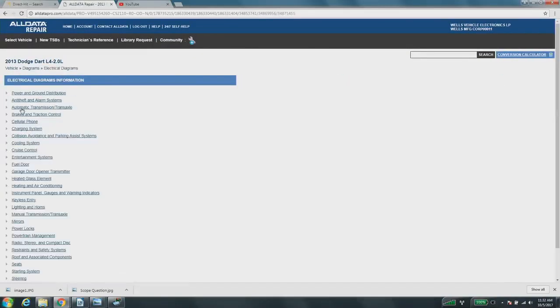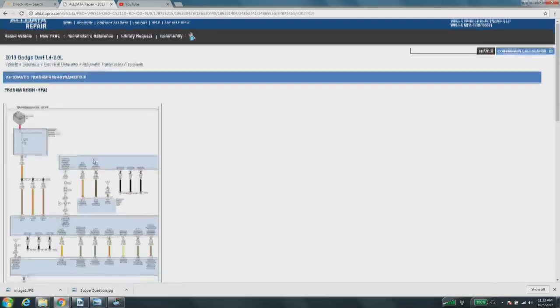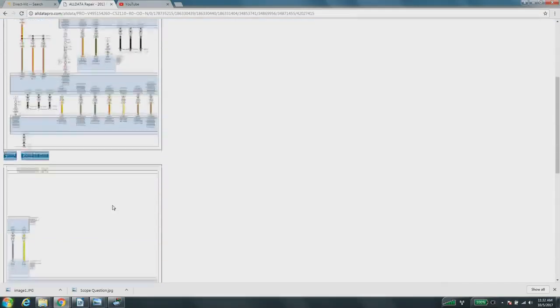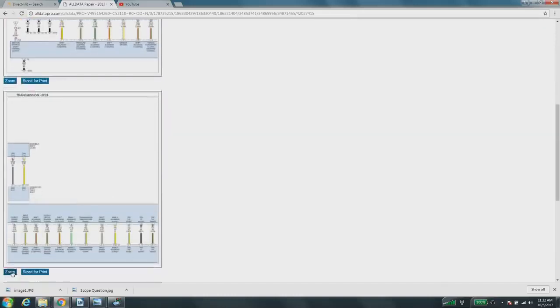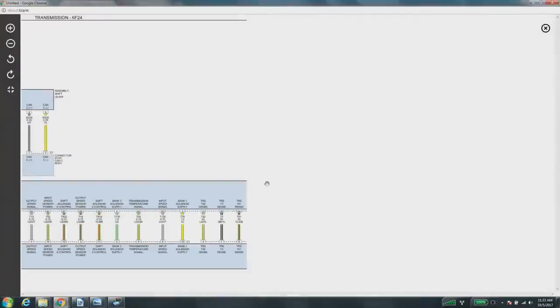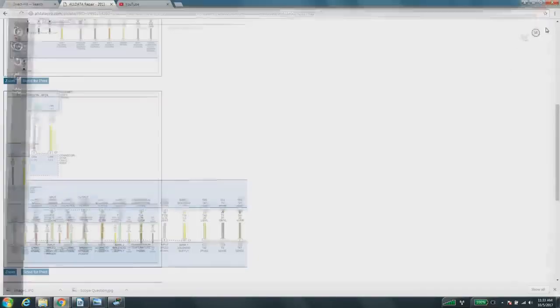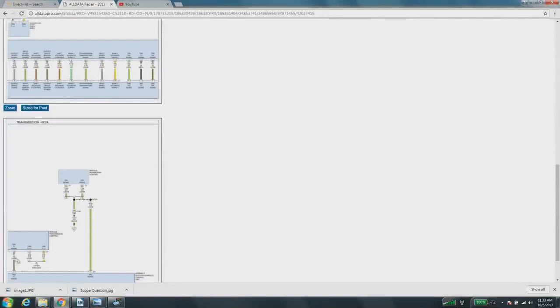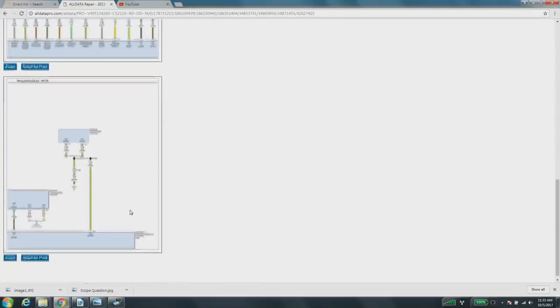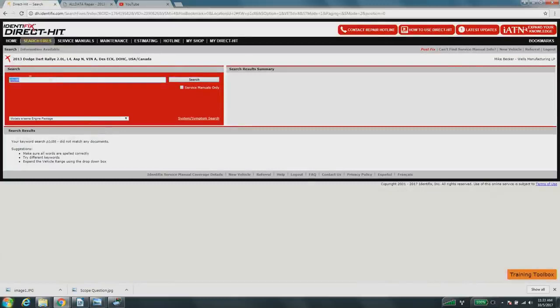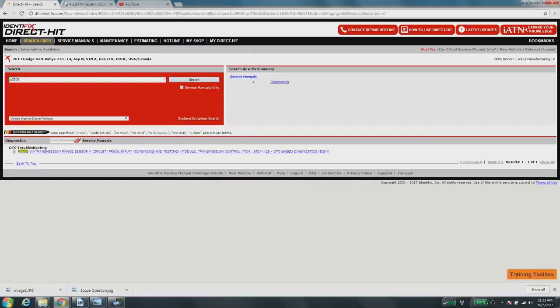So typically, this is where I would go: I would find a wiring diagram for this thing. And you're left with this. Just because I was here before, I'm going to skip ahead right to the second one. And we can see here's 3 of our sense circuits, okay? T42, T3, and T41. But unfortunately, that doesn't say park, reverse, neutral, or drive. So it's not really telling us, and our other one is right down here. It's not really telling us what exactly we're looking for. Fortunately, if we go a different route, let's go P0705, because that was our other code.